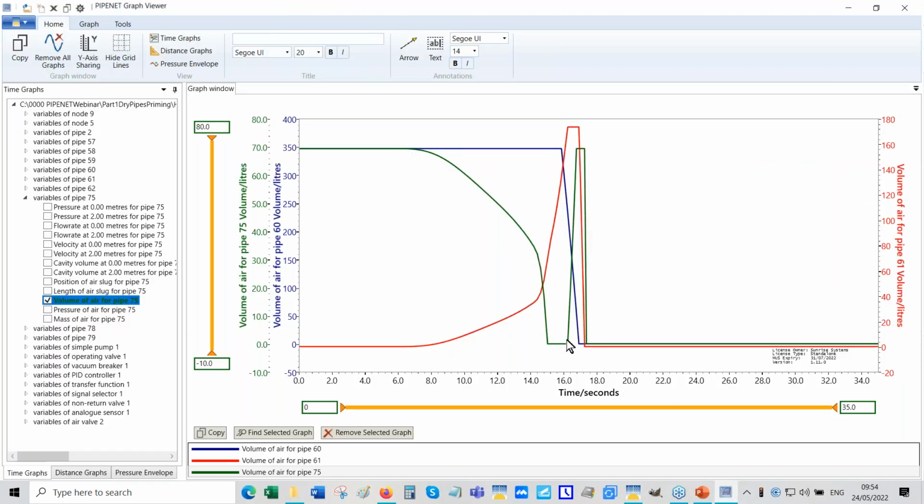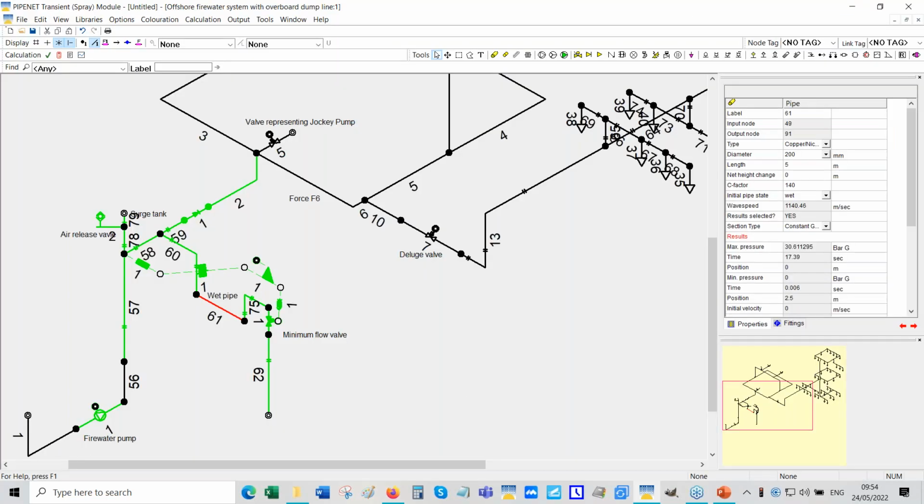And you see that green pipe, the volume of air increases, then goes to 0. So you can see this is a fantastic model. You can actually see how the air pockets move through the system. It's a very advanced model, very complicated. Okay, that's the three kinds of situations that you may encounter in modeling real systems where we use the cushioning effect and the air pockets.